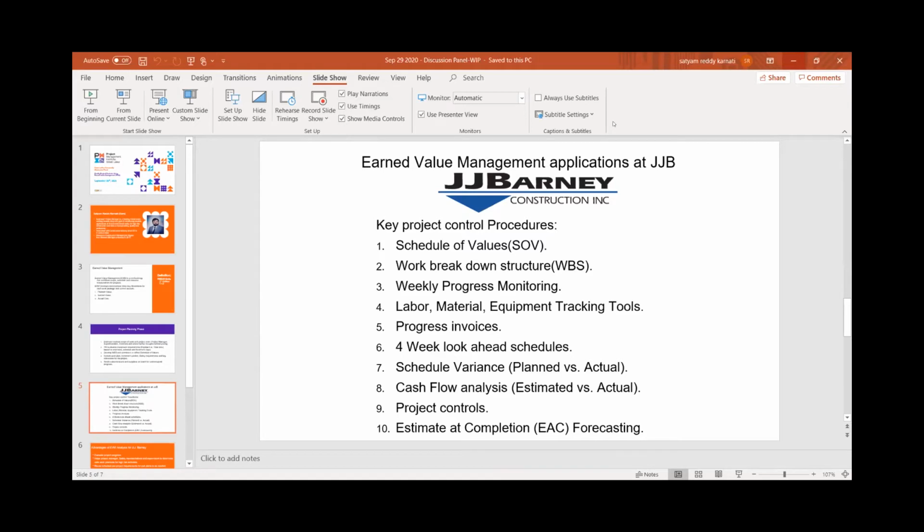In this sample, for example, I have installed 17.6 tons of steel out of 55. That's 34.51%, and that same percentage goes onto my schedule of values, and that's how I'm billing. Then for my installation, how much of these 17.5 tons have I installed? 12.6. And then excavation and backfill.